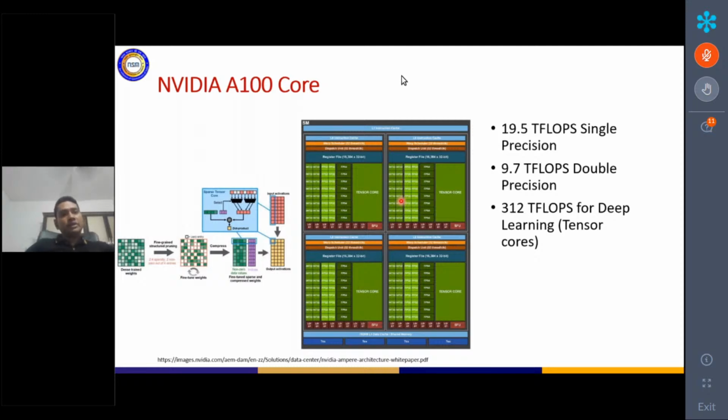So what is sparsity? Sparsity means you can have multiple weights or parameters which are very close to zero, and can be interpreted as zero. If you think from a computation point of view, if you have, let's say, a 4 cross 4 matrix multiplier, and half of the data is zero, then you do not need to compute that half of the multiplications.